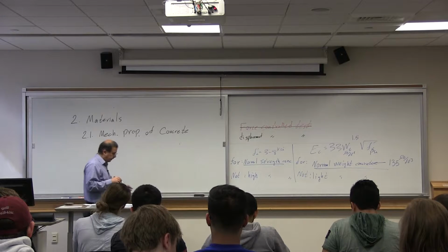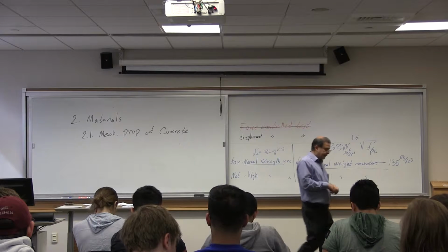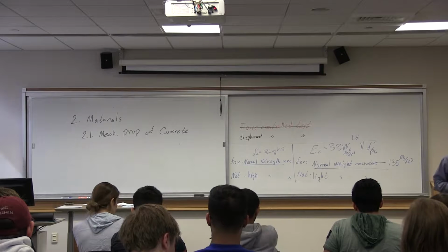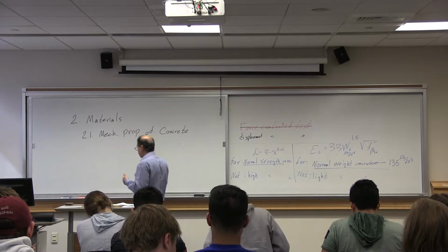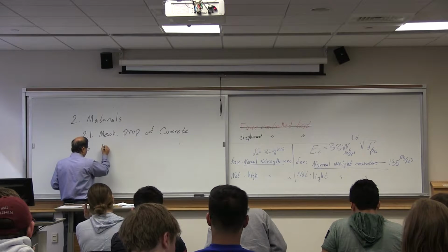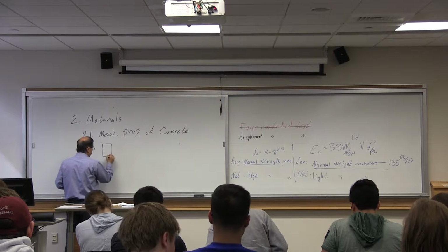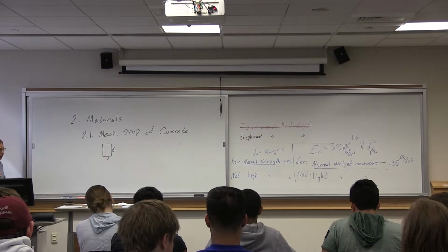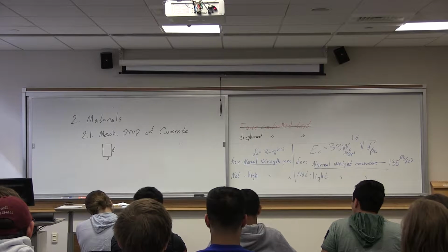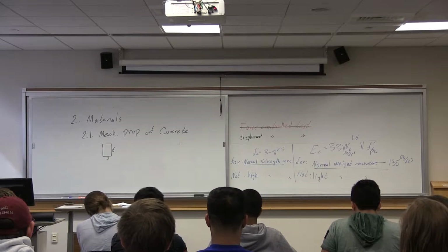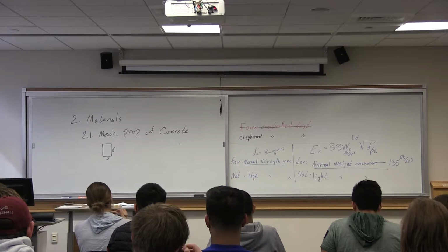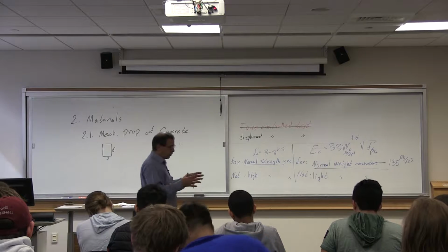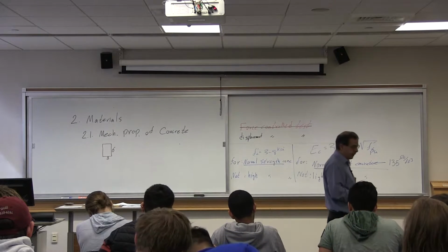Or maybe before going to concrete tensile strength, let me talk about concrete samples. The sample size that you used in your materials course was, I believe, 3 by 6. The cylinders are, again, historically in proportion to a 2 by 1 ratio. The height to the diameter is a 2 to 1 ratio. 6 by 3 is used because you don't use too much concrete, it's smaller and you can manage it better.